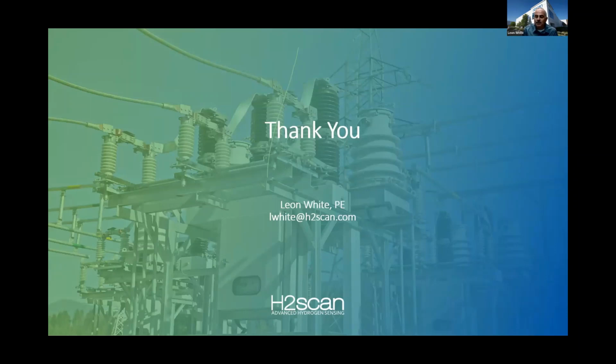It really depends on your circumstances, your transformers, and your experience. Some people have a failure rate of about 0.5% a year, some are up around 2 or 2.5%. So again, your experience, with not only the transformers but also the monitors, can allow you to extend the time between samples.